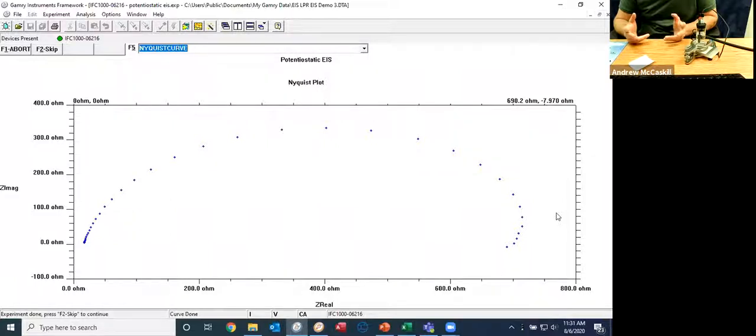Essentially, it's going to do the same thing we did for the LPR, but with a much larger voltage window. Without getting into too much detail, you can look up the information on how to find these pretty easily. From that experiment, you can tease out what your Tafel constants are going to be. And yeah, if you need any help doing that, give us a call. As I was preparing for this, I was thinking that's probably another good demonstration video: how to figure out what your Tafel constants are.